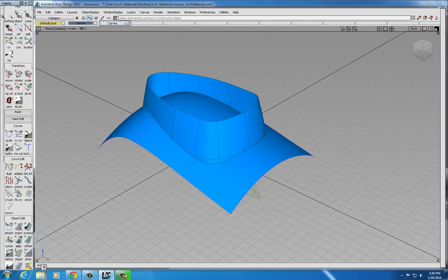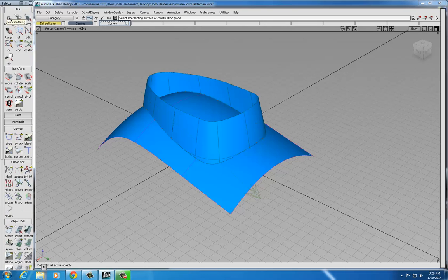In fact, you can even highlight this. If you go back up to the Pick menu, choose Pick Nothing, and then choose Pick Curve on Surface, which is the button on the third row down, the one in the middle. Just select it and then draw a box around everything, and you'll see it'll highlight the Curve on Surface. Curves on surfaces' only purpose, as far as I can tell in this program, are to indicate where a trim operation is to take place.